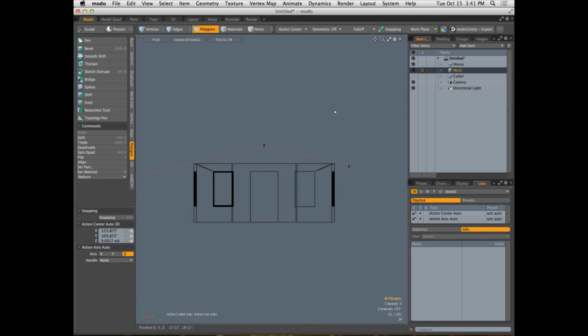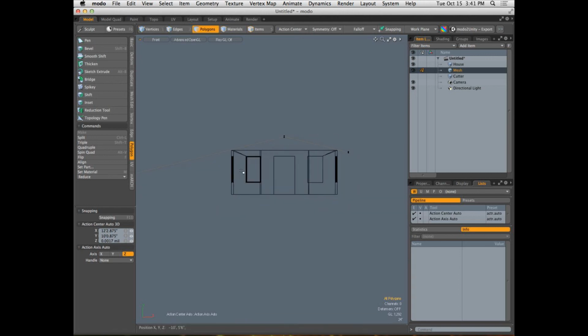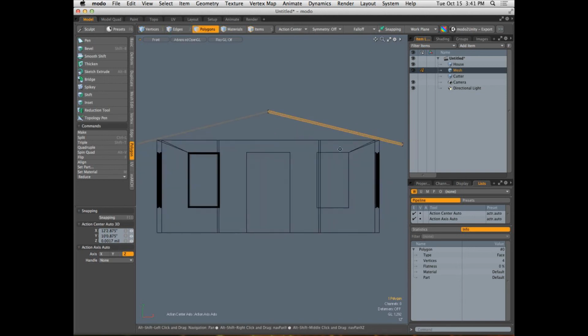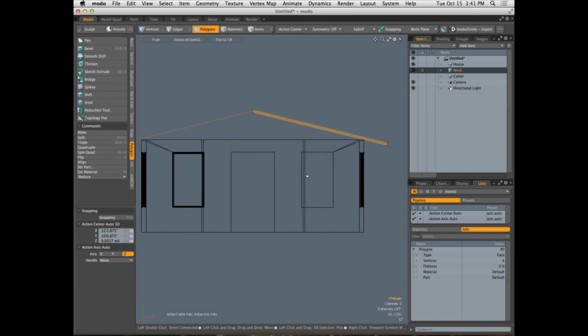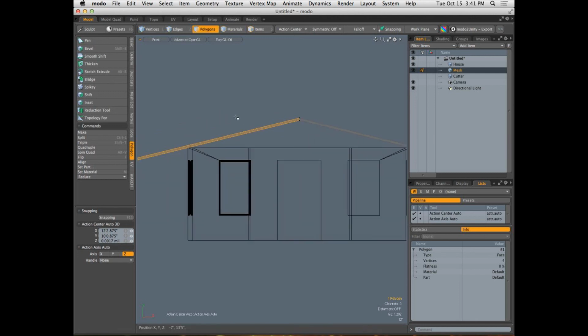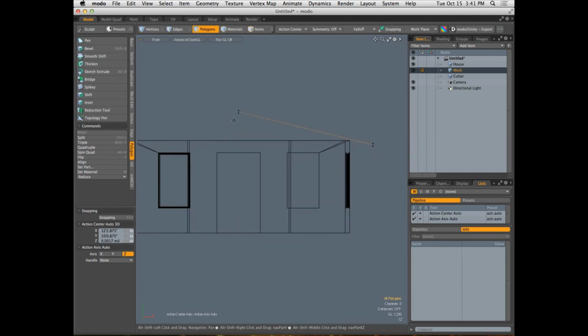All right. Now I have one side of my roof that's just dialed and perfect, and the other side of my roof that's not. What can I do here? Is there a way for me to have the right side, this over here, be automatically copied and pasted to the other side of the roof? Mirror. Mirror. Okay? When we mirror geometry, it's going to flip the orientation of it. I want to get rid of the one that I don't need.